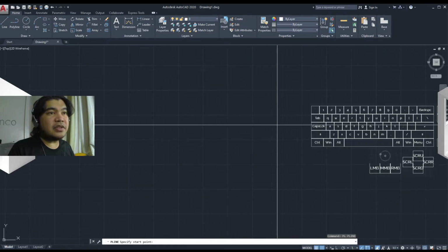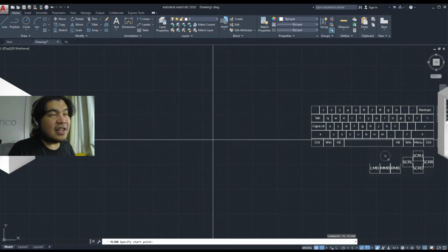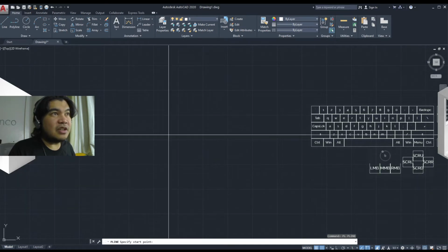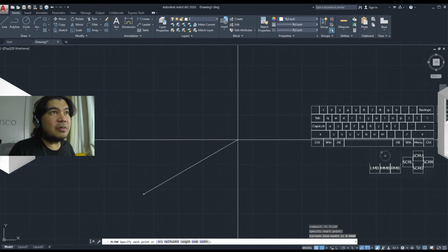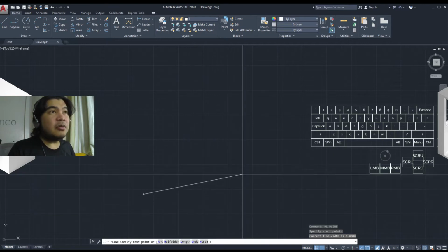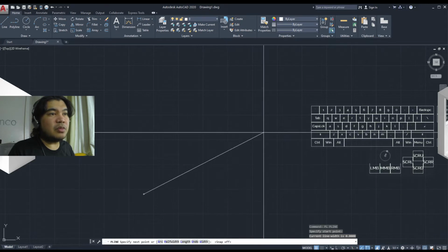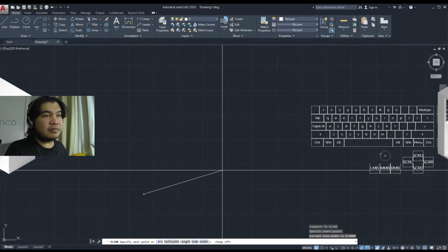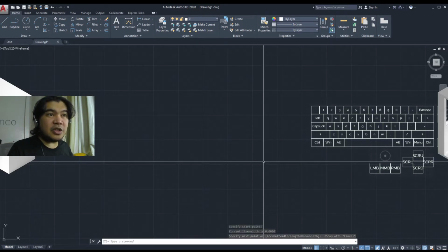So when this happens, understand that you might have hit F9 on accident, and that's why that is happening. Your control is less precise this way because it will keep on snapping to the grid until you disable it with another F9, wherein your line will be free to move all over the plane wherever you want it to go.